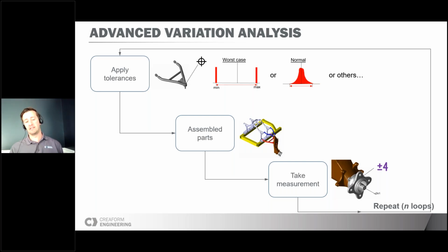And the second big step is really to assemble the parts together. And this is where it's important to know how it's assembled. So if you know, okay, I have a bolted subframe to the mainframe, I'll allocate the subframe, but the software also sees that, okay, I have a clearance hole between my subframe and my mainframe, then I have a clearance and my subframe will kind of float onto my mainframe. So within the assembly method, the software can capture those kind of variation,